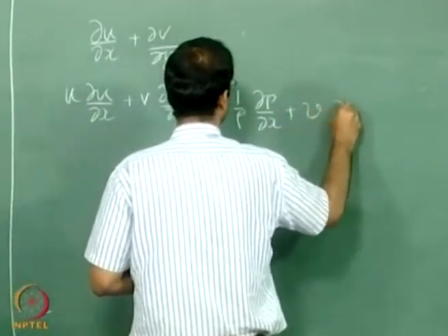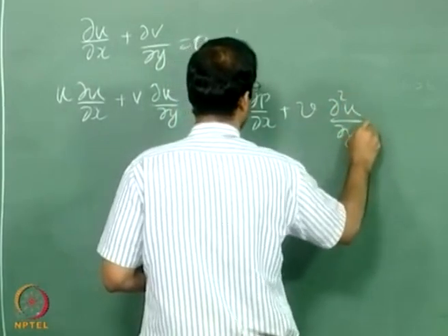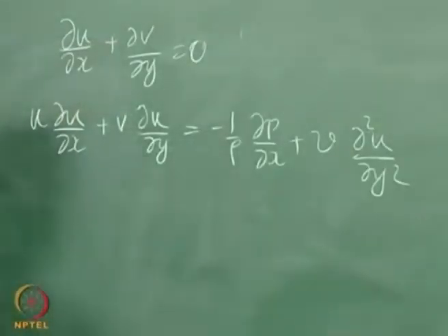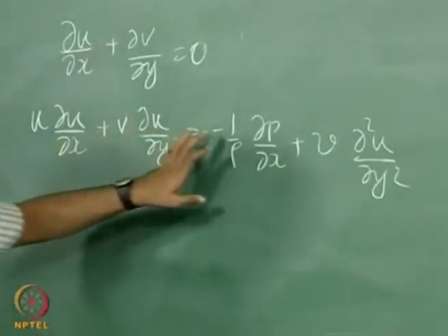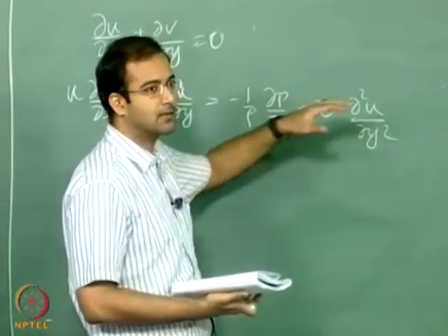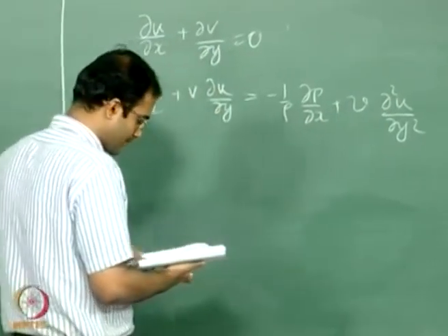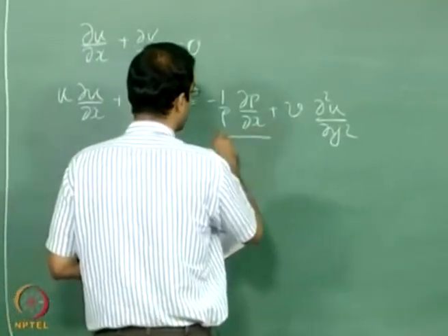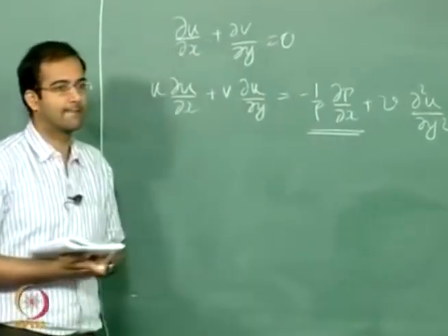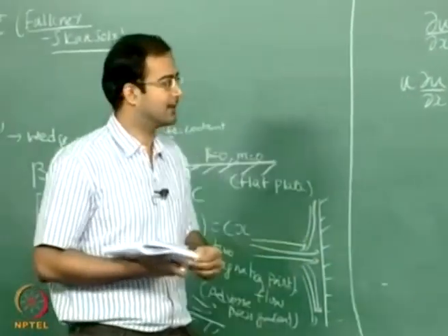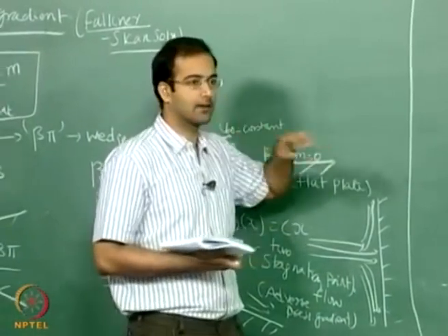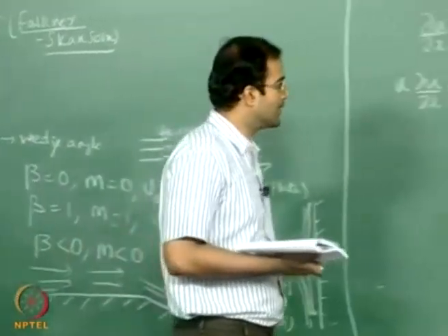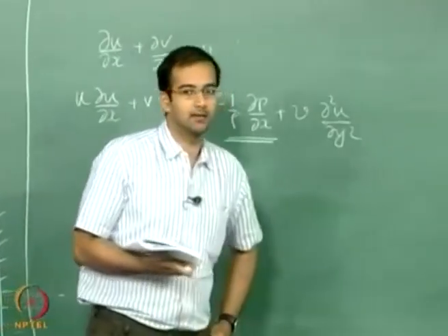We have not yet written the energy equation. First we will take the flow solution and then we will apply that to the energy equation. So this is your governing equation. Now we all know how to calculate the pressure gradient. I probably mentioned this in the third or fourth class, when we derived the governing equations for the boundary layer. So how do we evaluate the pressure gradient inside the boundary layer?